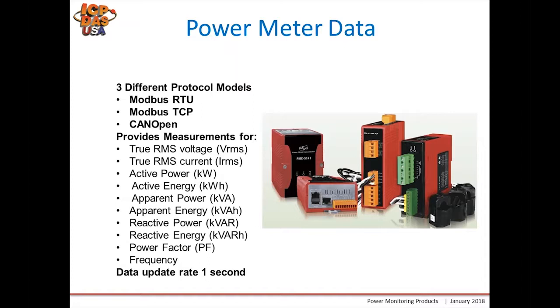The three protocols again: Modbus RTU and Modbus TCP are two of the most common protocols. Modbus RTU is over serial communication, RS-485, and Modbus TCP is over Ethernet, and the CANopen protocol is communicated over CAN bus.